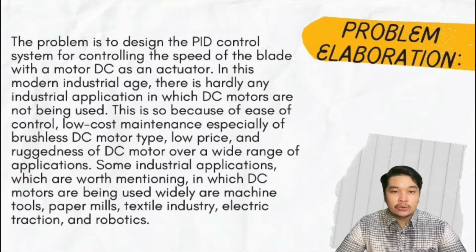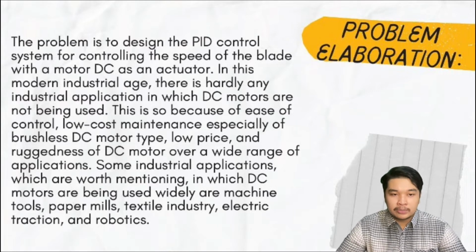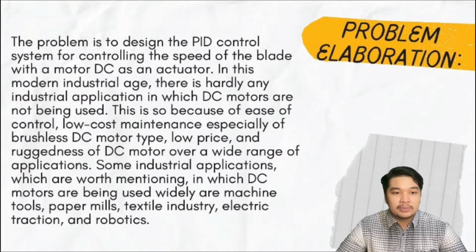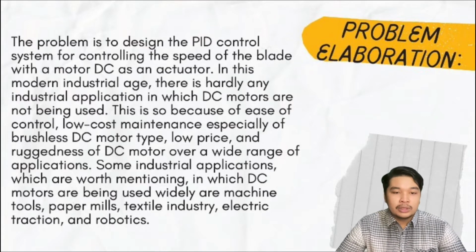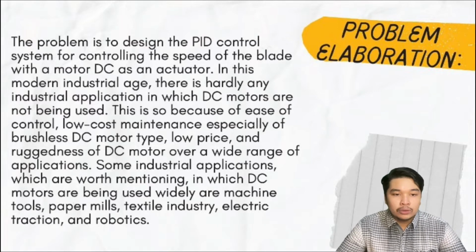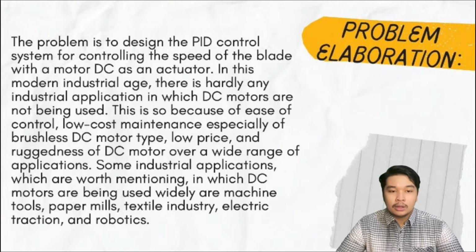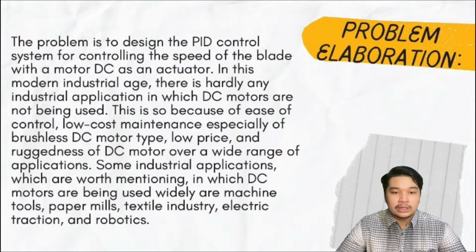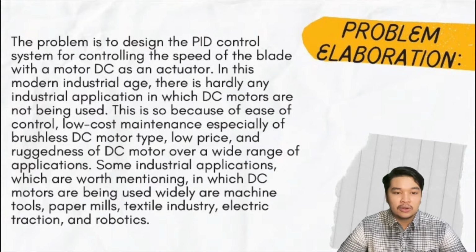The flexibility in controller design of DC motors is due to the fact that armature winding and field winding can be controlled separately. This gives excellent speed control performance over a wide range of desired values. There are different types of controllers like lead lag, linear quadratic regulator, PID, and sliding mode control that can be incorporated in control applications. The PID controller is one of the earliest and best understood controllers, incorporated in almost every industrial control application due to its efficiency and ease of implementation.